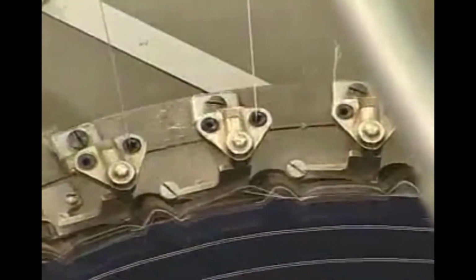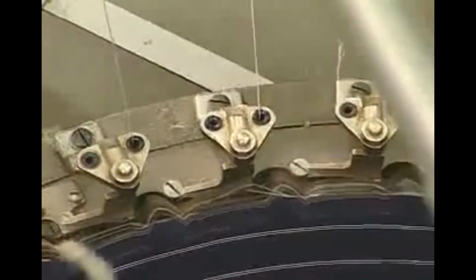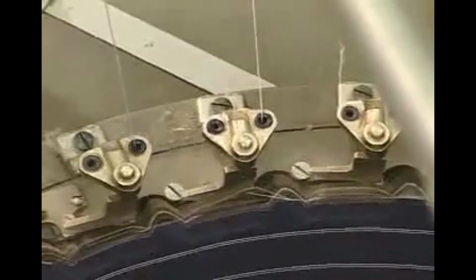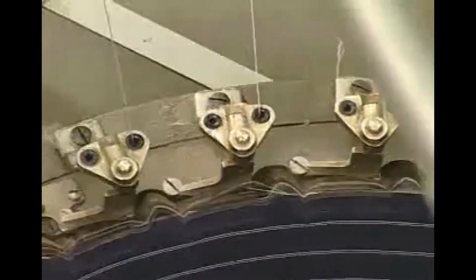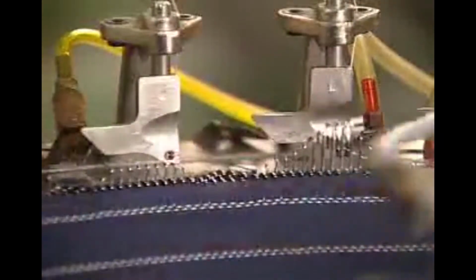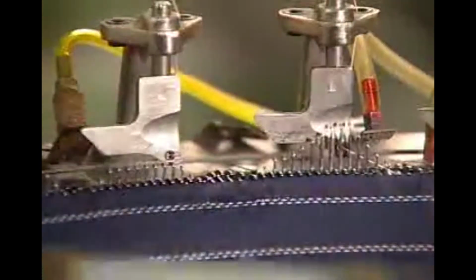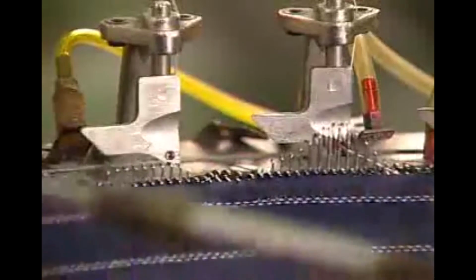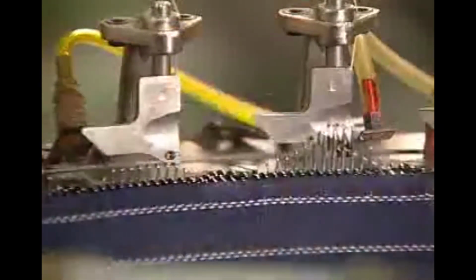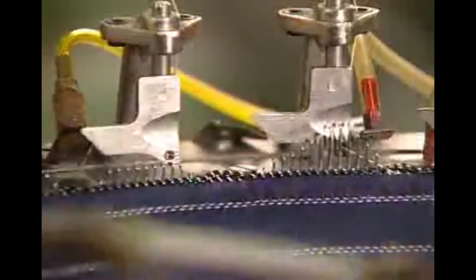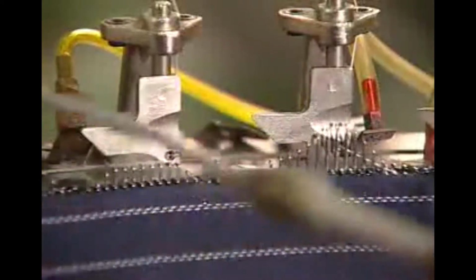The intricate action of knitting, where needles form loops, occurs at the middle of the machine, between the take-up and the yarn feeding mechanism. A close-up shows you how, with circular weft knitting, needles knit one after the other in a sequence for each yarn. Notice how loops are formed horizontally by needles knitting around the cylinder, forming a tube.